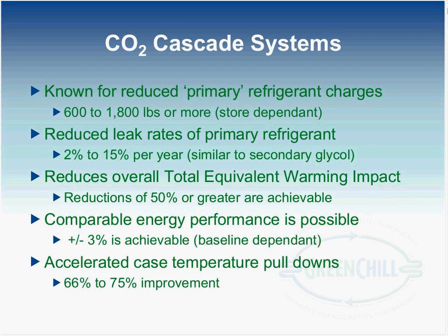It also reduces your overall TEWI, which is short for total equivalent warming impact, by impacting the direct portion of the emissions rate used in the calculation, and 50% or greater TEWI reductions are achievable. You'll get comparable energy performance, anywhere from plus or minus 3%.